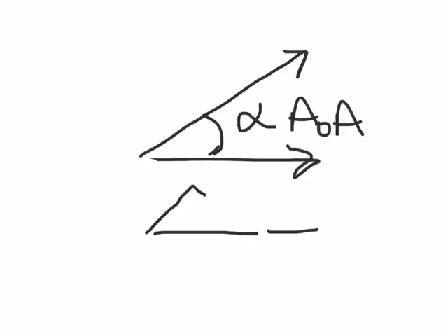The elevator is going to move up, and if the elevator moves up, there's going to be a downward force that's going to act upon the tail surface, okay? And then the nose is going to pitch this way, and we call this a pitching moment.